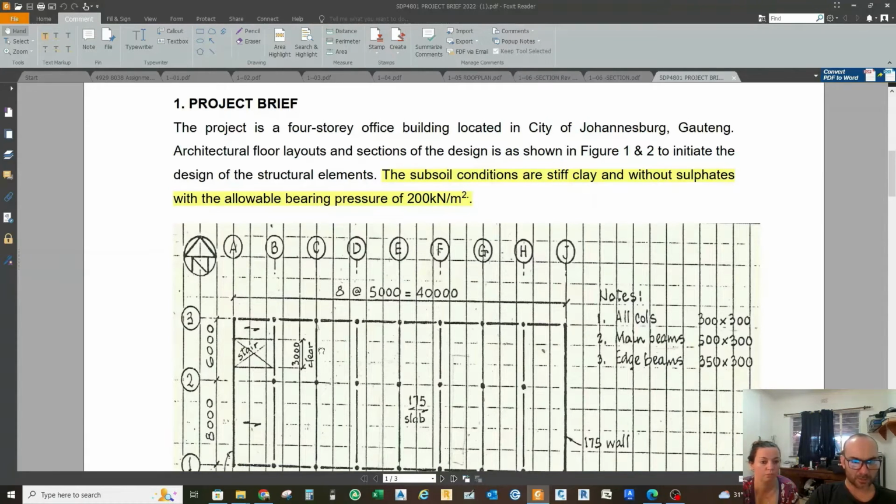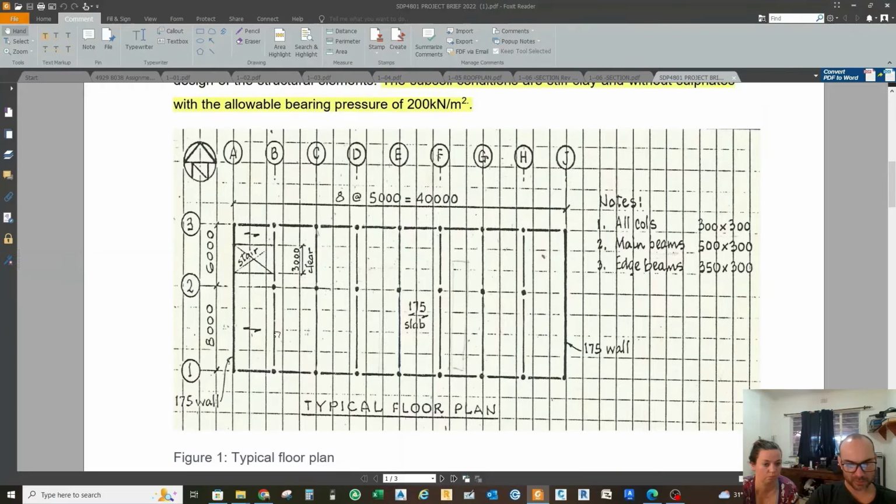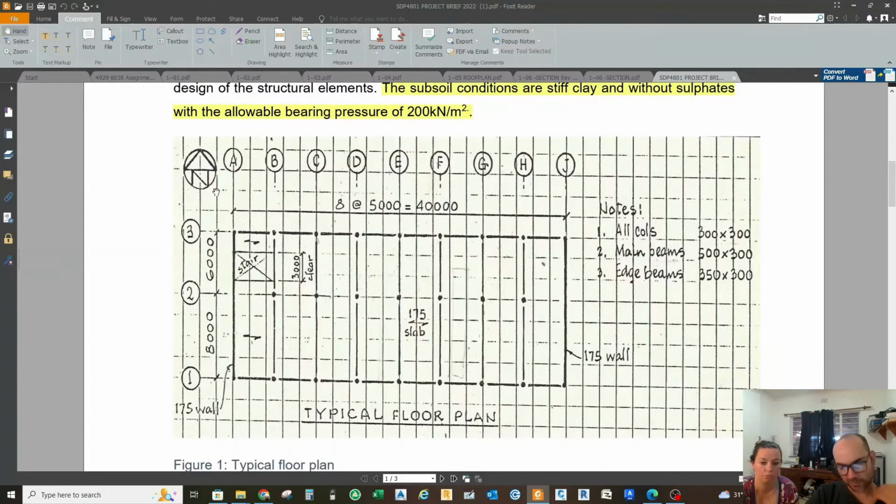This layout was then taken further, it was reviewed, some rules of thumb were generally applied, and then slab spans and thicknesses were all verified by calculation. As you can see, there are no internal walls shown yet, so before the loading for the structure could be developed and calculated, especially for the dead loading imposed by the walls onto the floors, a wall layout had to be generated.